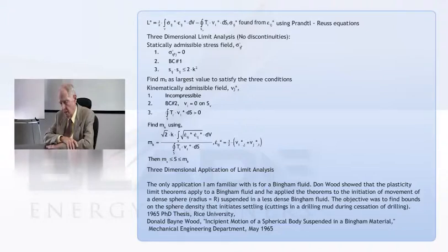I, at one point in my life, was very interested in things called Bingham fluids. Now, a Bingham fluid, the easy way to explain it is, it's got a yield point, but once you exceed the yield point, it's exactly like a linear viscous fluid. So there's none of this stuff about that lambda parameter and all that.